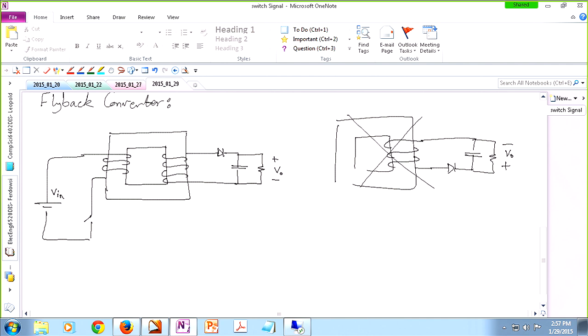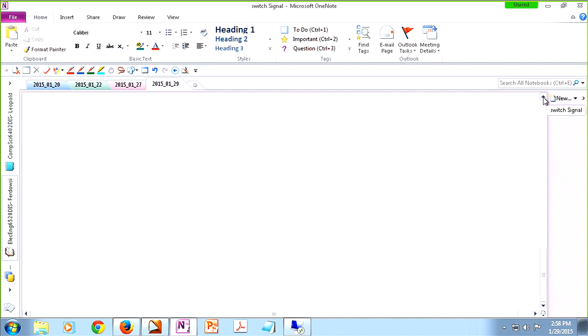So if you have taken electromechanics or something like that as an undergraduate student, you know that we call it a transformer or a coupled inductor. Basically, there's a complicated model involved for these guys that represents the leakage inductance on the primary side, the leakage inductance on the secondary side, leakage resistances, core losses, things like that. We don't use those comprehensive models over here. All we do is we just model this coupled winding with one magnetizing inductance and an ideal transformer. Okay, so let me redraw it now. So now I'm using a circuit model for my coupled inductor.